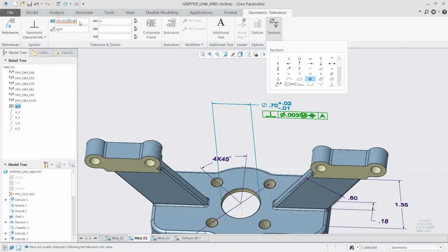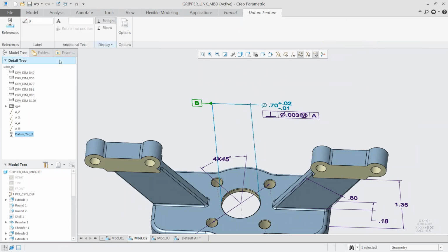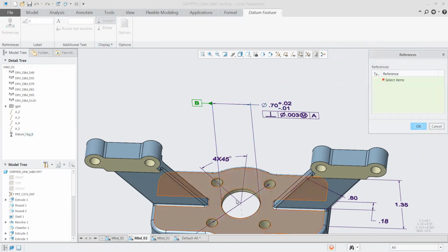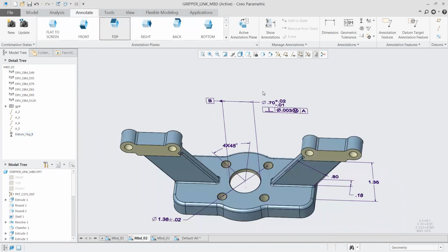You can see there, if you added in one that wouldn't make sense for our scenario, it throws you an error, says, hey, that's an invalid symbol you added in, just making sure that your values are correct in that sense. And as we did before, we need a datum tag. So for that one, we'll just pin it on the width line. We'll also add in the surfaces that we want to reference within that datum, and should be good to go there.